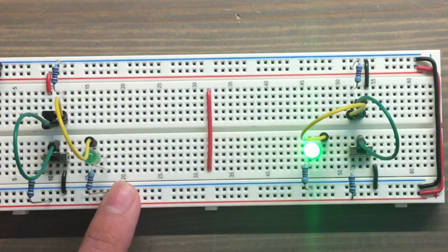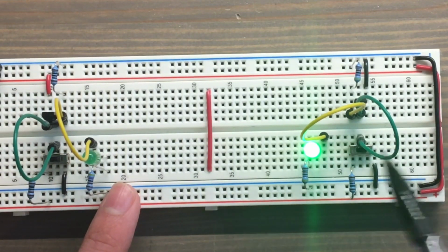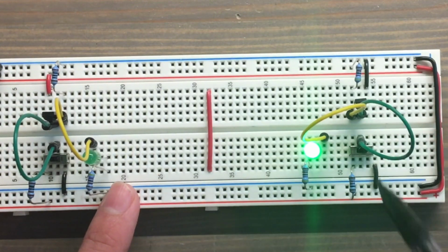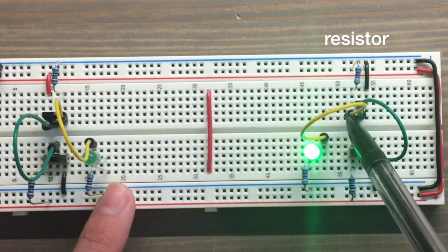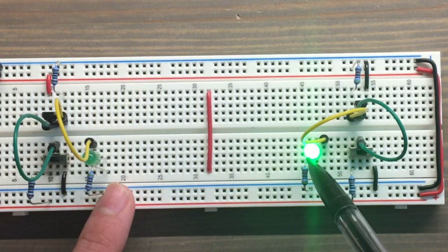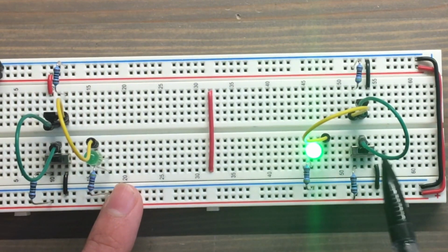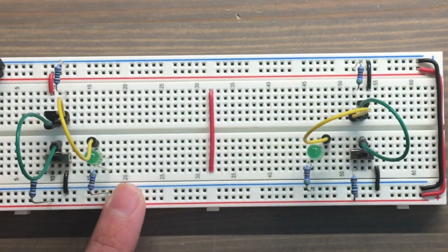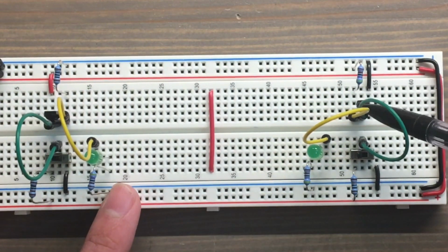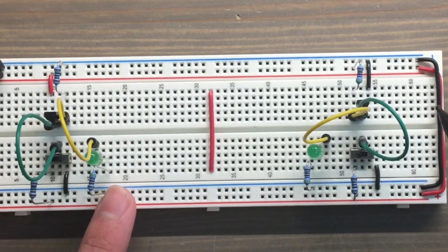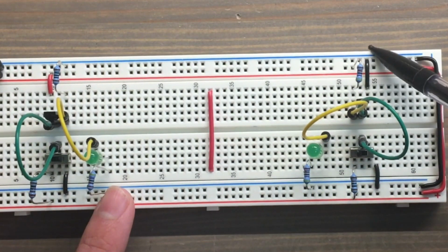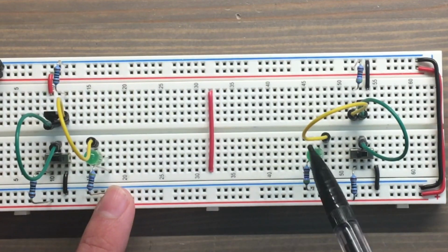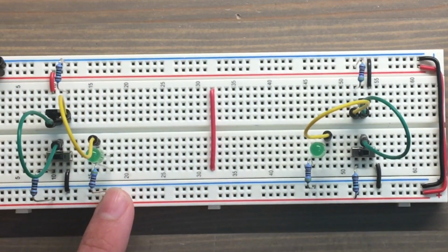Now, this gate is also pretty simple. Right now, when the LED is on, the power is just going through this LED here and through the wire to the LED. But when we switch this switch on, power can go through the transistor here, and the easiest path for it to take, since there aren't any resistors, is just to go straight to ground through here, so it takes that path and the LED turns off. And that's a NOT gate.